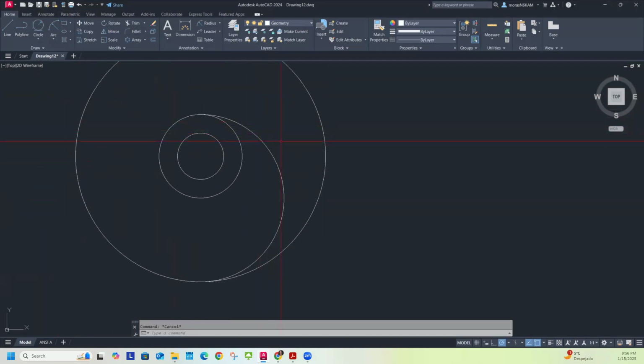Okay, well, this one here is creating the curve that I need. So I'll go ahead and do the polar array. So I did the start and radius, and then I selected this quadrant, the bottom one, and I input the radius. And now I'm going to do a polar array, and I'm going to just count how many I have.